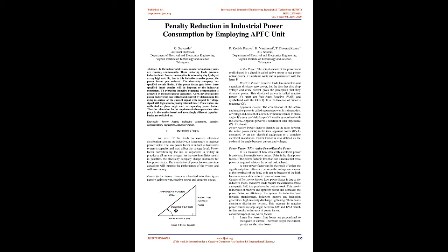The APFC device reads the power factor from line voltage and current by determining the delay in arrival of the current signal with respect to the voltage signal with high accuracy using an internal timer. These values are calibrated as phase angle and corresponding power factor. Then the calculation for the requirement of compensation takes place in the motherboard, and accordingly different capacitor banks are switched on. Keywords: power factor, inductive reactance, penalty, compensation, capacitors, capacitor banks.